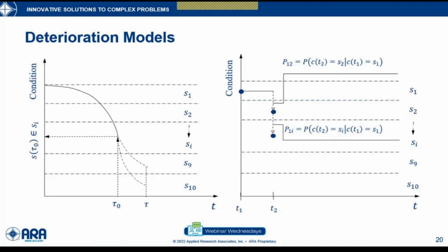So, following on that, deterioration models that you could use can be discrete in nature, but keeping in mind the continuous process in the background, and that you're discretizing the domain of condition that we have, for example, 0 to 9 or whatever condition state, is important when it comes to assessing these probabilities. So you should understand that when we're doing deterioration models, there is a probabilistic and uncertain nature, and part of that comes from that discretization process.